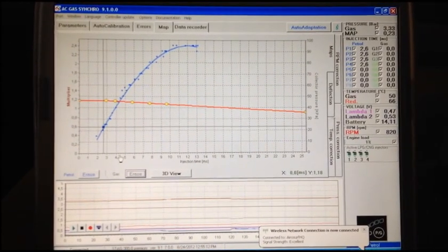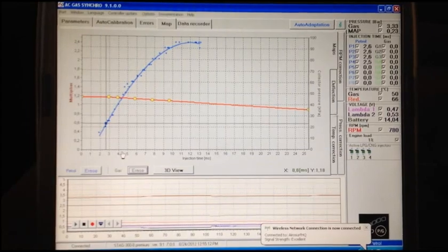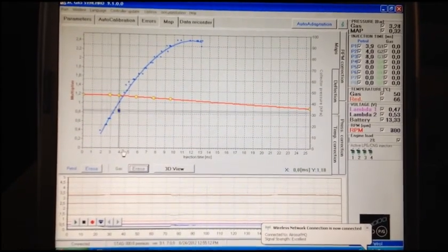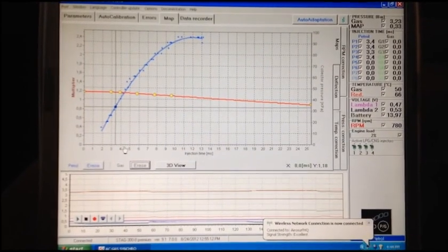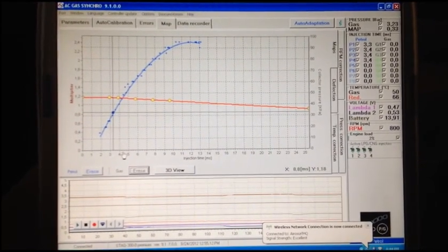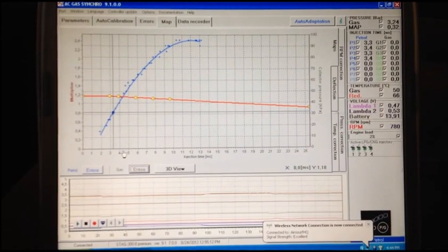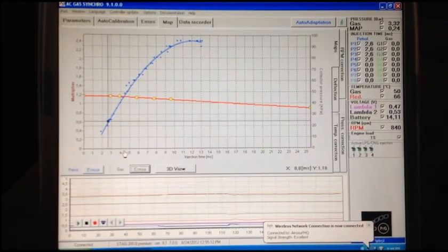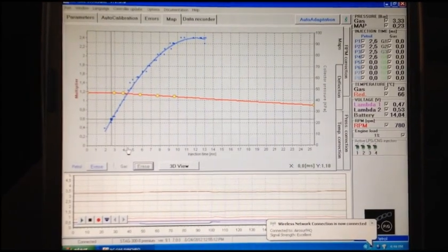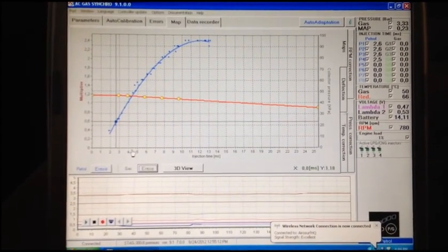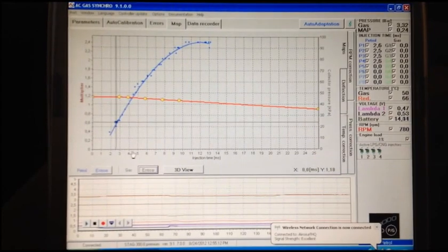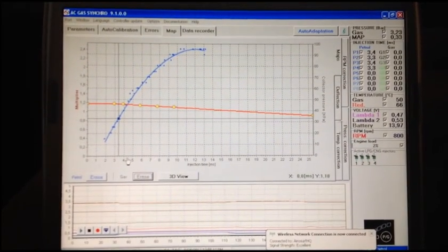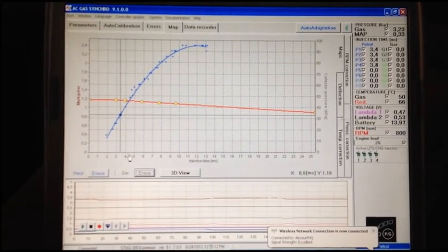If there's a certain temperature that it got into, and your tuning was off, it's constantly collecting data from your fuel trims on board. And if you have that interface, whenever you're doing this corrections part that we're doing here, it does it more accurately. Instead of just off of the injector pulse width, it's also taking into factor your fuel trim corrections directly from the gasoline computer, and it'll get it more accurate.